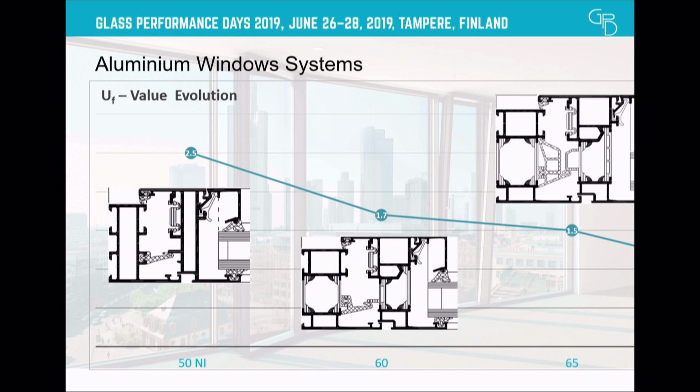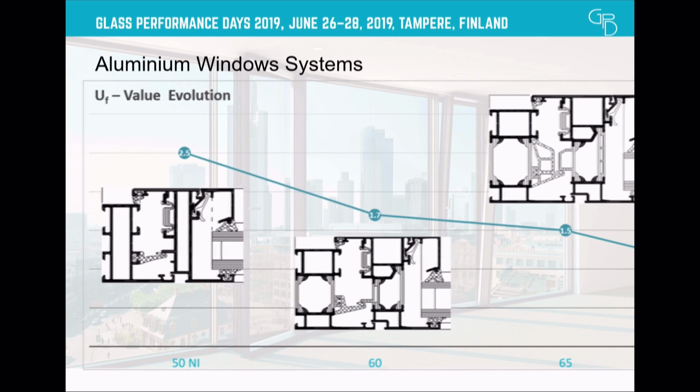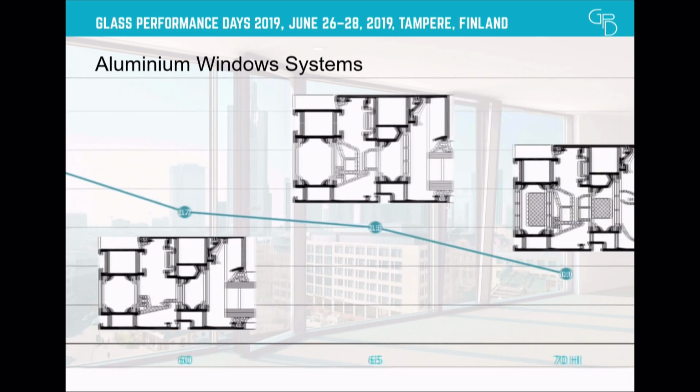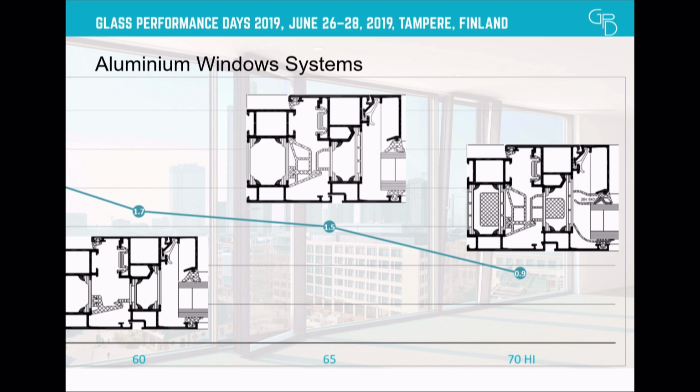So that has been driving. That trend of sustainability has been driving for sure the development of our window units. Back in the day, we started with non-insulated windows with a depth of 50 millimeters. When we talk about 50, 60, 65, we talk about the depth, and the depth is relevant to get increased insulation properties. So we incorporated insulation bars and increased the depths, following the trends, to go deeper and deeper with the U values of the frame, ending up with a high insulation property material.